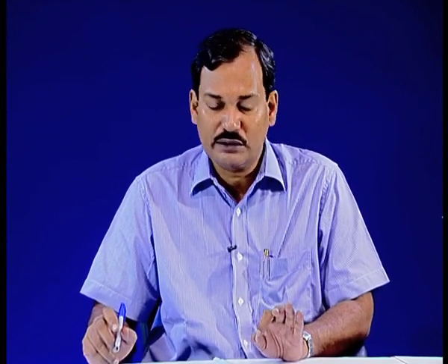So, the next step is simple, you divide both sides by del x del y del z, taking the limit when all of them approach 0, and the result that you are going to have is del x of n A x plus del y of n A y plus z term plus R A is del rho A del t. Is that clear to all of you? It is just a species balance, the same way we have done for the equation of continuity. So, I am writing the equation of continuity for species A inside an imaginary control volume del x del y del z fixed in space. So, it is a fixed coordinate system.